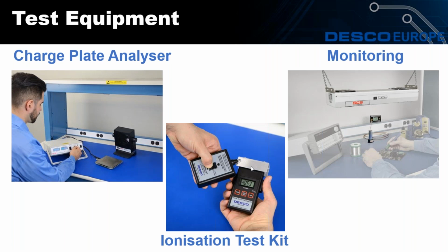As Stephen said, and as we've been going through in the presentation, if an ionizer is producing more positive than negative, you're actually inducing a charge onto the work area. These direct current ionizers, the industry standard ionizer, rely on sharp emitter pins, the high corona discharge pins. All areas have dust, some more so than others, and because of the high voltage on the sharp point, it attracts dust and debris to the emitter pin, and as that builds up, it will affect the output of the ionizer.